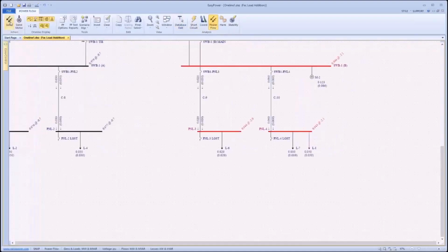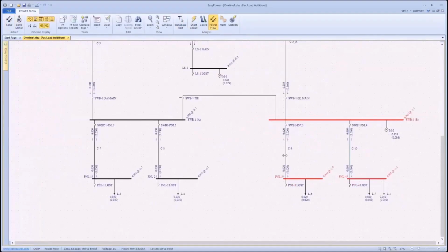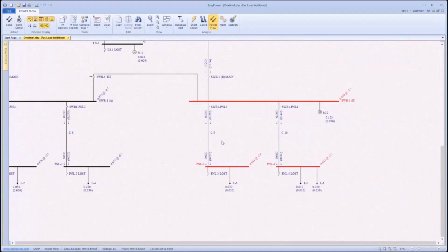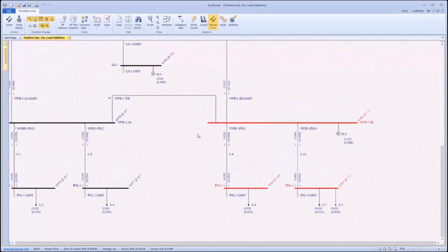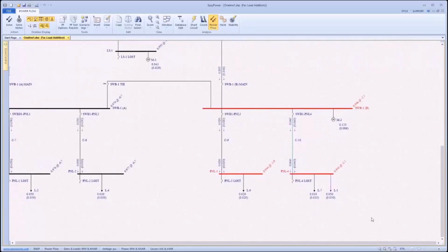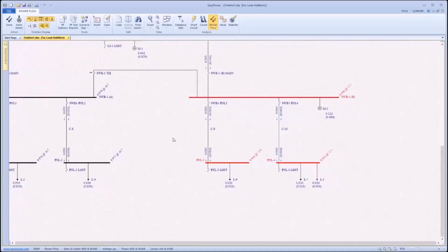Let's go to power flow. Let's solve it. So we've got some voltage drop issues, but we could play with this. This is an actual facility that had been appropriately designed and not put together for a webinar. It probably would have been a little closer there, but it looks like we're just over the amount of voltage drop we have set for our thresholds there, 5%, I believe.